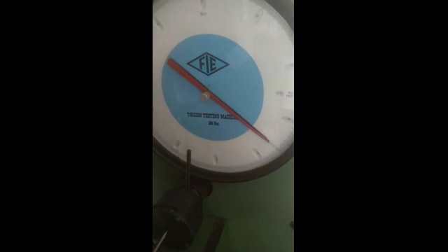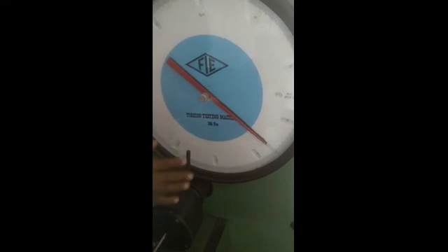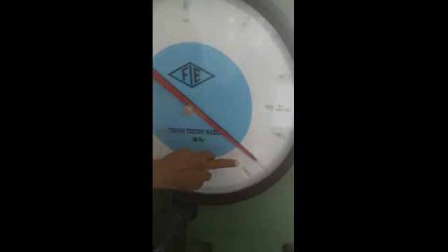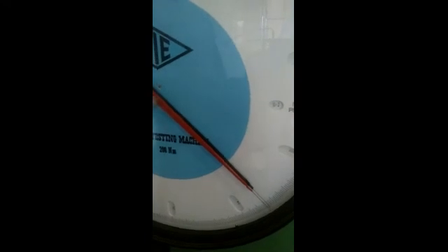So if we see, it is taking some time to move further. Now it has stopped at one point. If you see the dial, it's not moving further. Whatever degree you got on the dial, that we have to take, and whatever torque we have got here, that we have to consider as the upper yield point. So this is the reading you require the most in your experiment. So we got the upper yield point.